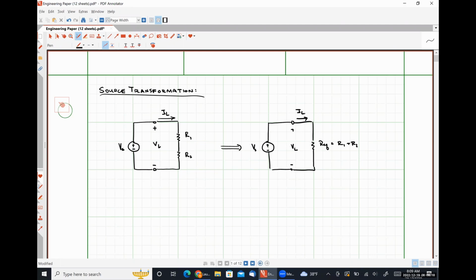We have already seen this by combining resistances. We could do something similar, putting resistors in parallel, voltage sources in series, current sources in parallel, etc. Okay. The rule that I'm trying to establish for the concept of electrical equivalence is that things are going to behave exactly the same. So our source effectively cannot tell the difference between two resistors in series or a single resistor that is a combination of the two, as long as the voltage drop over the network is the same and the current flowing through the connected network is the same.